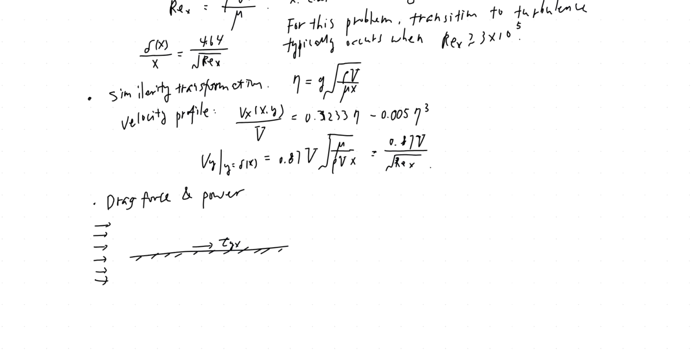It is symmetric, so you have shear stress on both sides of the plate. Then the drag force on the plate would be twice, one from each side. You integrate from 0 to W. Well, since it's constant in W, you don't necessarily need to integrate over W; it's just multiplied by W, the area. And you also need integration over L, from 0 to L.